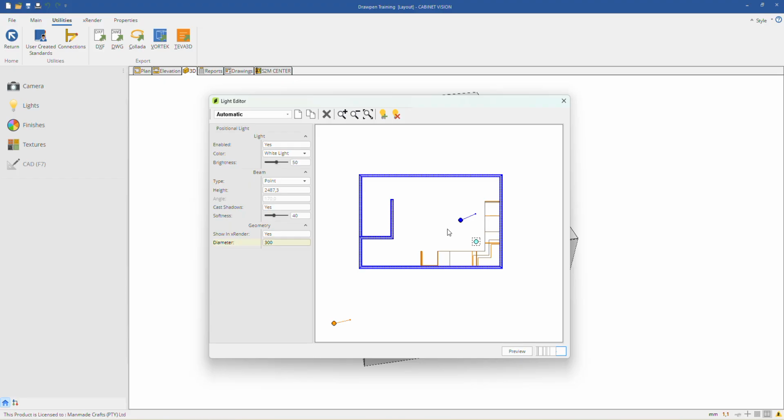to show you what the spotlight is. I'm just going to add another one. You'll see now, I just want to show you quickly, it is a little bug that they're still trying to figure out. If I add a new light, it doesn't show all of the options. If you press once on the beam, it'll show everything else, then it refreshes and brings in the rest. So you'll see now, geometry is not there.